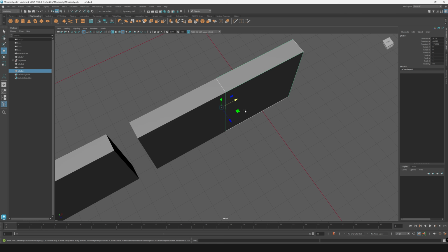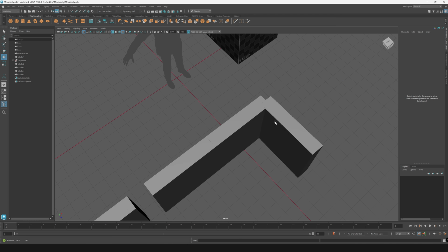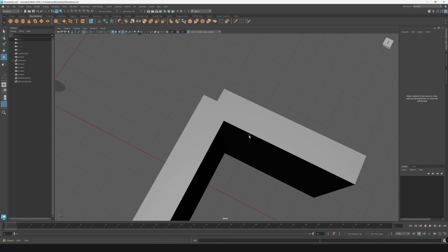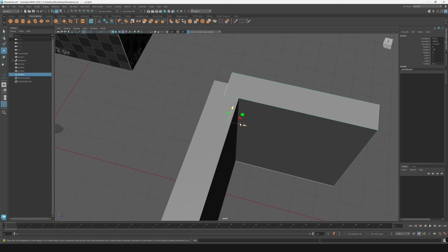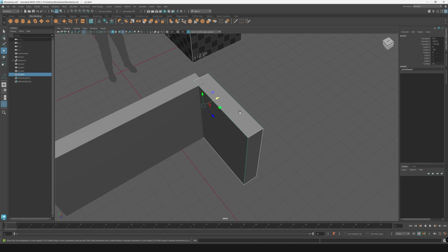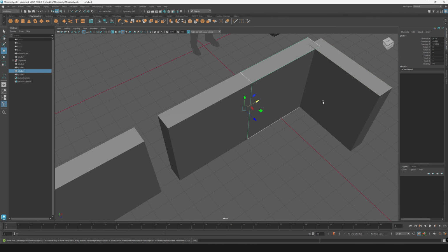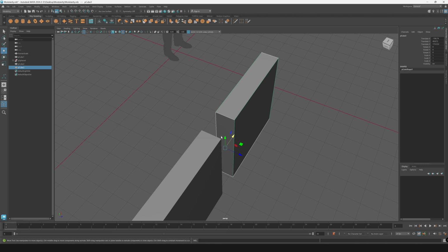But what if I want to duplicate him again, and then start turning him, like start to make the next wall? Well, I don't like any sort of weird Z fighting if I don't have to. I don't like this where they're overlapping like this. It's just not good. And also, he's again in the middle of the thickness of each object, so it's probably not best to have our pivot point be in the middle here as well. So maybe we already moved him to the side, so let's move him to the front like so. So let's hold D and V and move him to the front.